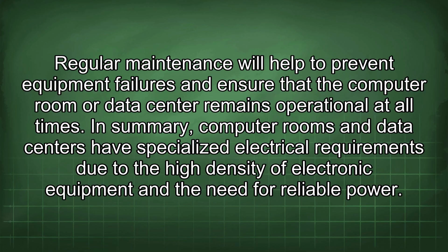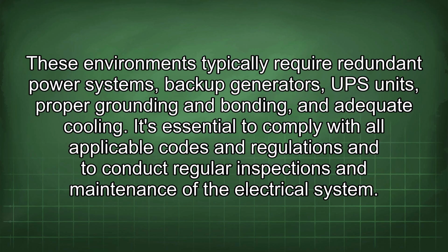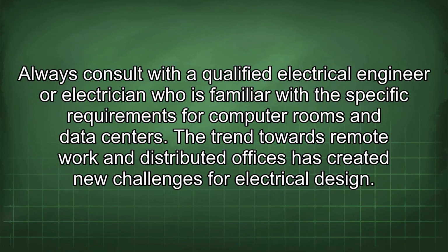In summary, computer rooms and data centers have specialized electrical requirements due to the high density of electronic equipment and the need for reliable power. These environments typically require redundant power systems, backup generators, UPS units, proper grounding and bonding, and adequate cooling. It's essential to comply with all applicable codes and regulations and to conduct regular inspections and maintenance of the electrical system. Always consult with a qualified electrical engineer or electrician who is familiar with the specific requirements for computer rooms and data centers.